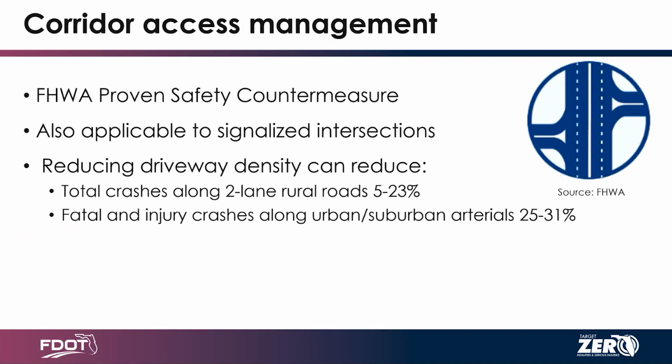We already mentioned access management, but it's also applicable to signalized intersections. Thinking through more of the corridor, reducing driveway density can reduce total crashes, especially in more rural area types. It can also reduce fatal and injury crashes, because if you reduce the number of driveways, you're reducing the number of conflict points along a corridor.